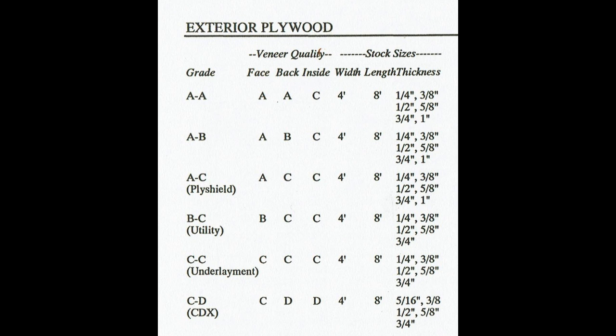BD is your construction go-to. It can be used again as a lower substitute for the AB paneling, as long as it's painted. CD is your generic subflooring that you'll typically see in housing or construction, and it's great as a base for tile work, linoleum work, or carpeting.